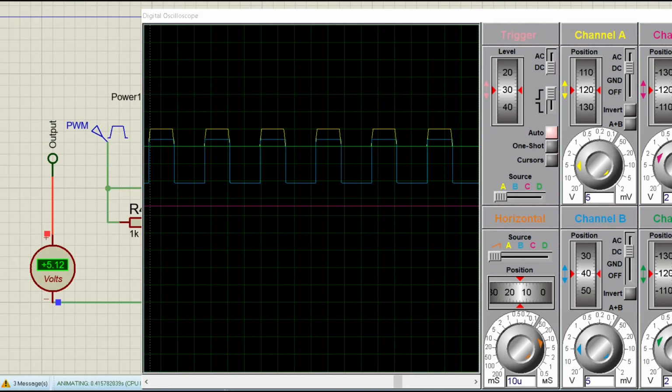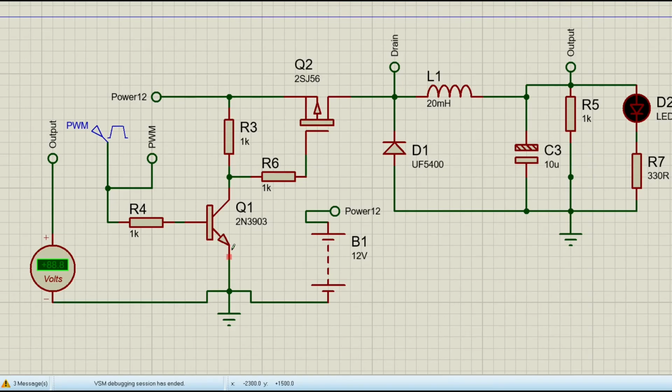So what we learned in this video is that choosing your components must be realistic. You must take into account the sizing of the components. You cannot use a 10 Henry or 20 Henry inductor. It's not realistic. So you have to use smaller inductors, but to use smaller inductors you have to switch at higher frequencies. So using frequencies of 20 kilohertz, 30 kilohertz, maybe 60 kilohertz will make it easier for you to